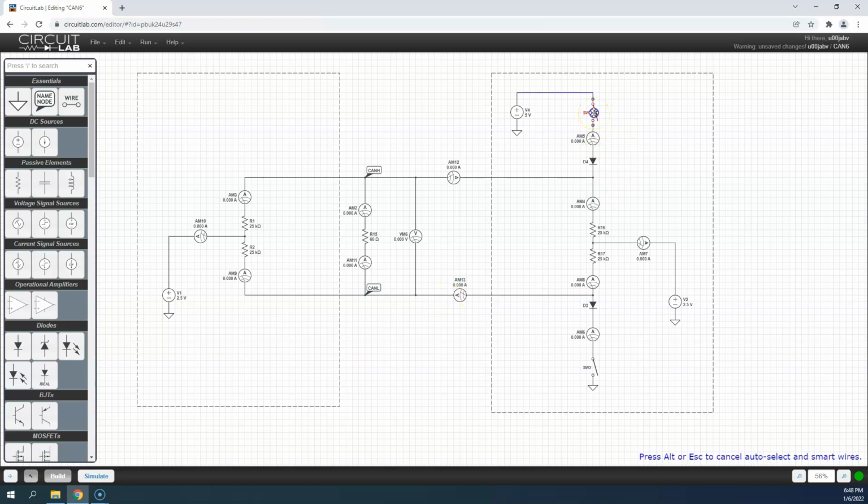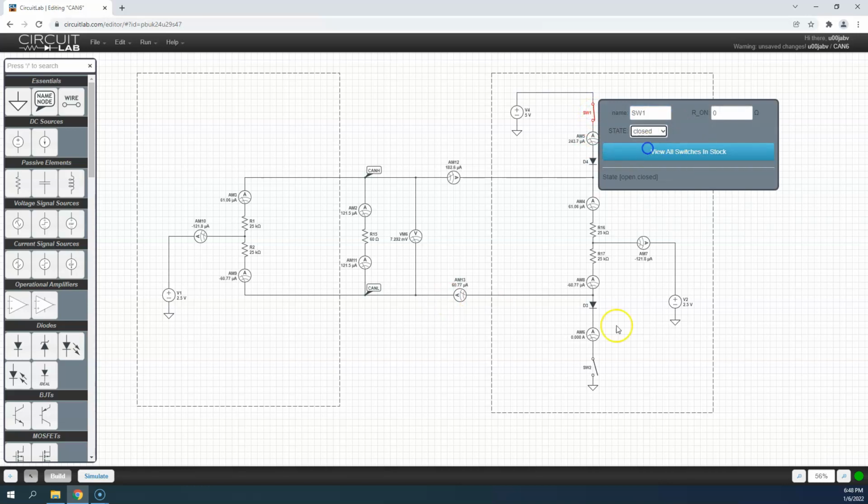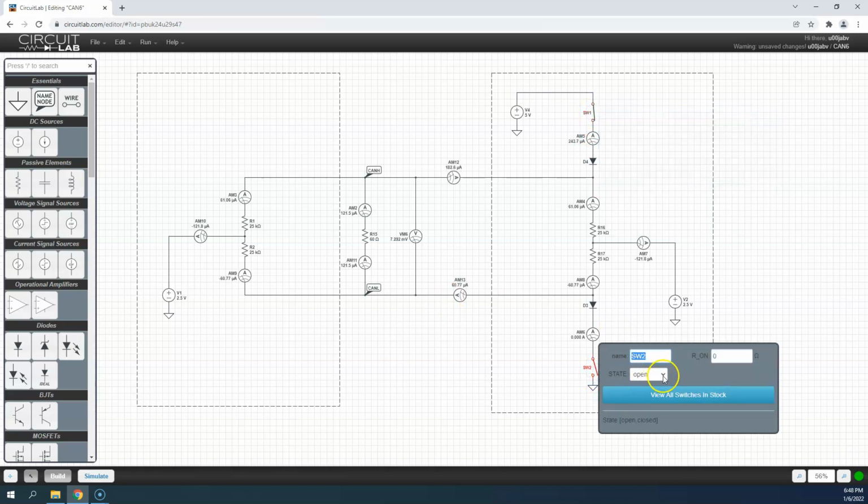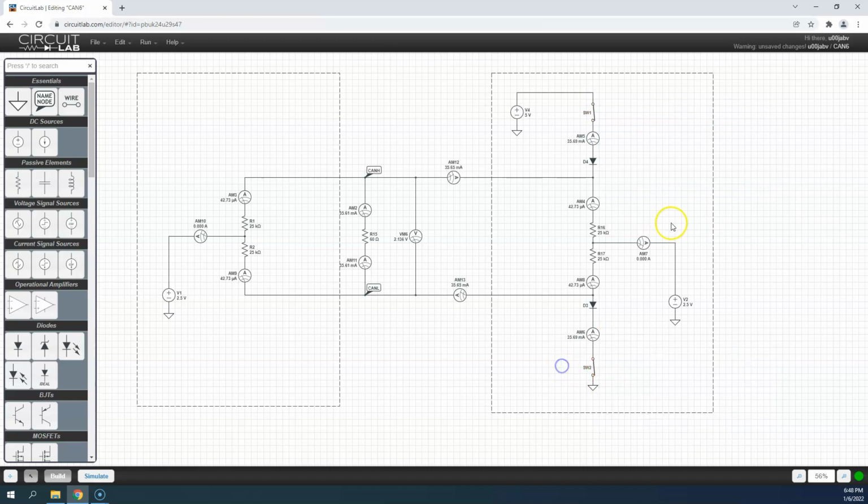So I'm going to go ahead and close the switches. Let me get both of them closed before we look at this, because we always close both at exactly the same time. Let's look at what's happening now. My meter shows a difference of, so this is the dominant state. This is this CAN transceiver driving the bus to dominant state. The other one over here is at a recessive state. Once we drive to the dominant state, we get our voltage difference of 2.136. We consider this a logic 0.